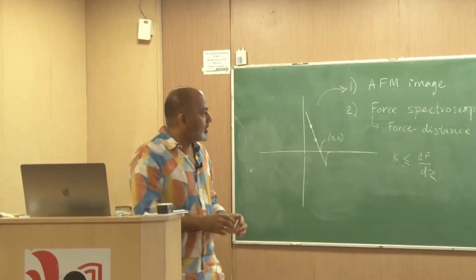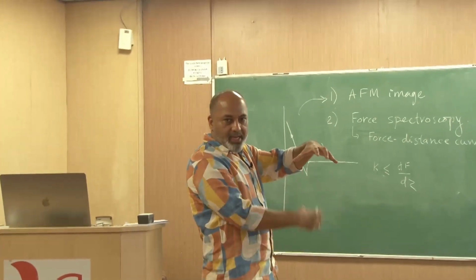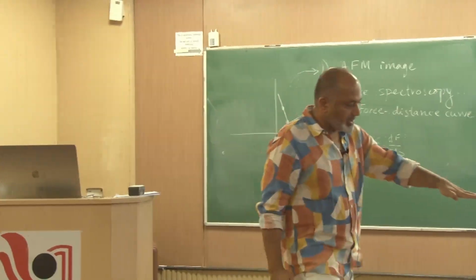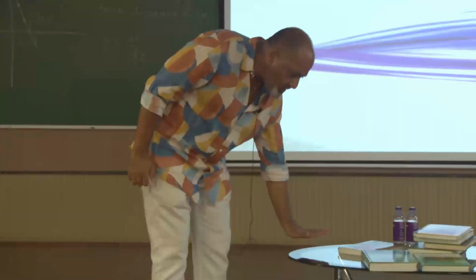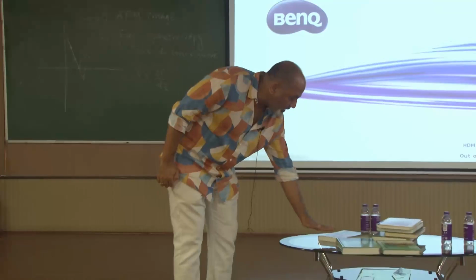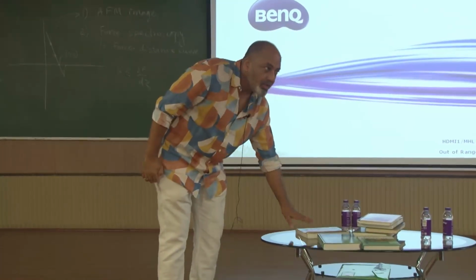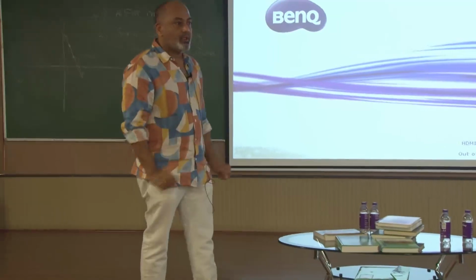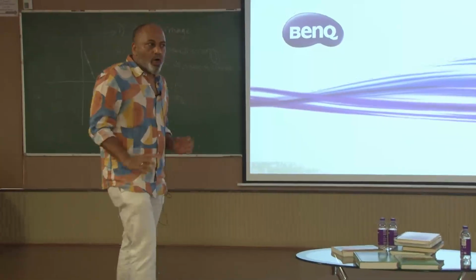It takes time to load, but you saw that the sample was kept on this scanner piezo, right. So, you got the cantilever that is coming here, once again bent upward at 1 nanonewton, and if I go there it becomes 1.2, the 0.2 difference, which means I have to pull this whole thing down by how much?